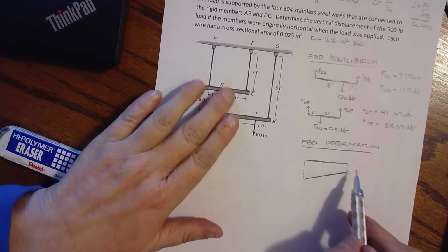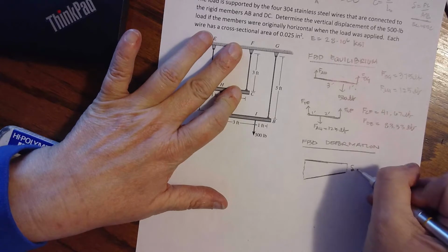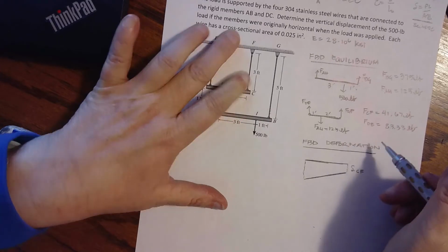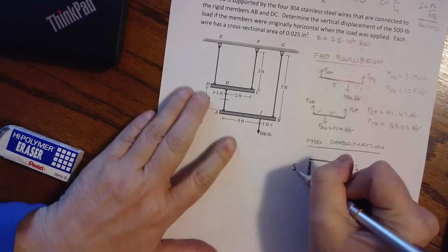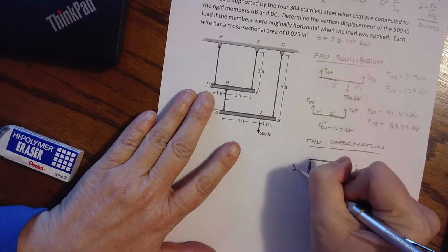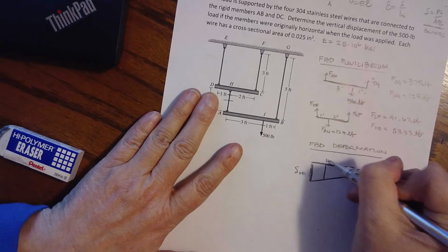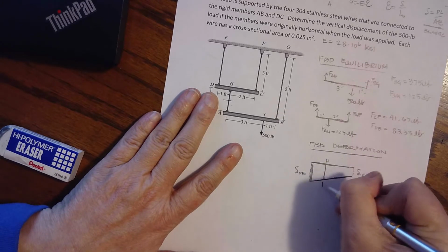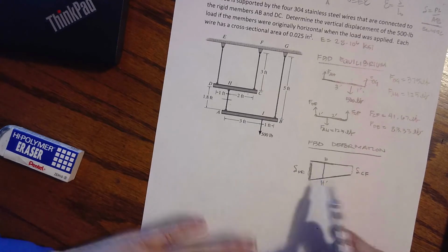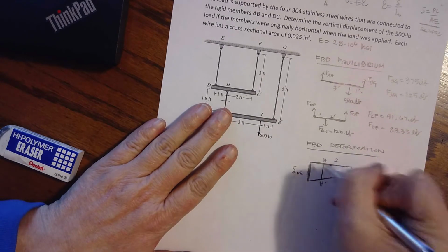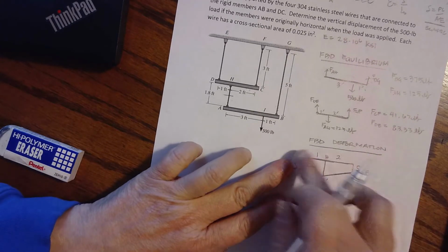Okay, and I know that this displacement here has to come from the change in length of cable CF because there's nothing else above it. And this displacement right here has to come from the elongation of cable DE. Okay, and then this point H is just going to go along for the ride. It's going to move from H to H prime because we are just moving on down, and it's going to come at a ratio somewhere between these two, 2 and 1.